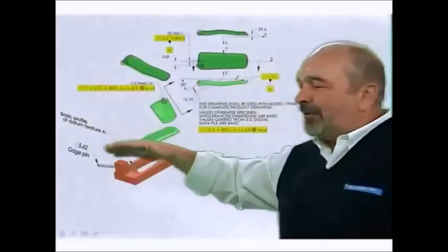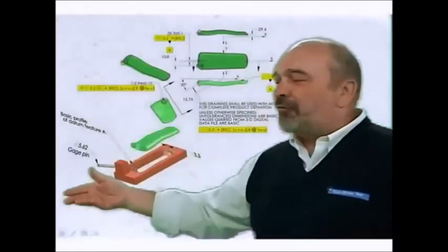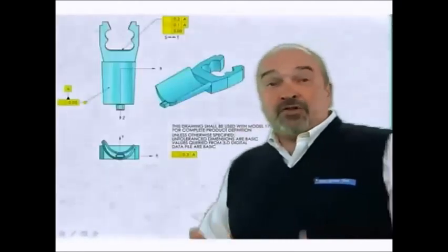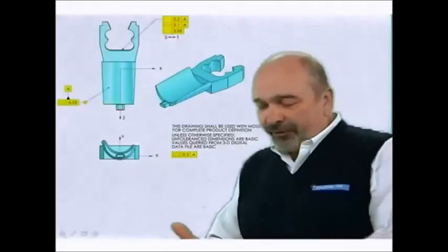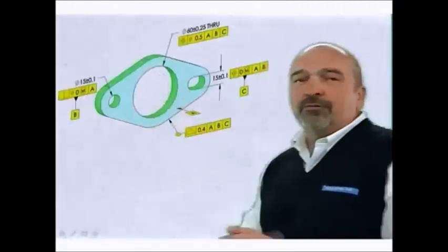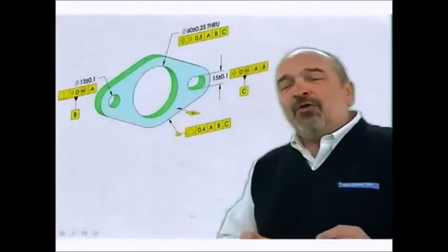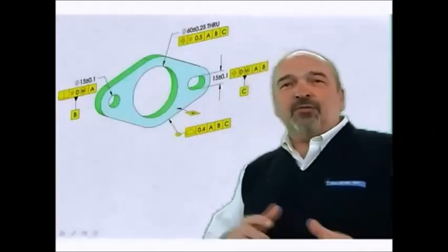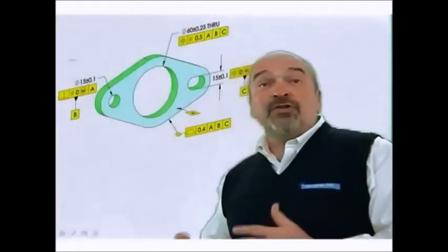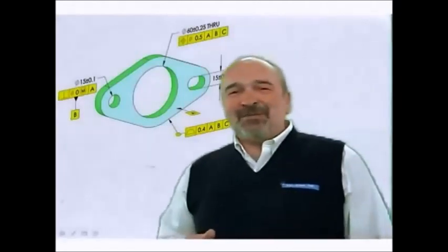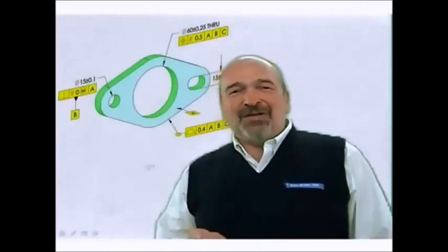On this complex shape now, this is back for a cell phone. I can use that complex saddle as a datum feature. They've expanded the composite tolerancing in position and profile. Here we're seeing several tiered composite profile. And my favorite, the Y14.5 standard ties in with the Y14.41 standard, which allows us to embed our geometric tolerances in our 3D model.